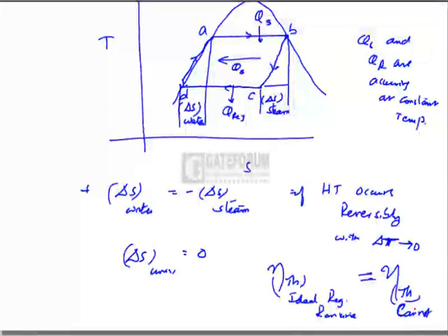No, it is not practically feasible, because when the steam is transferring heat to the water, it becomes too wet, the dryness fraction greatly decreases, and such wet steam is not suitable to expand in the turbine because it will cause turbine blade erosion. So the ideal regenerative cycle is only an imagination whose efficiency will be equal to that of the Carnot cycle.